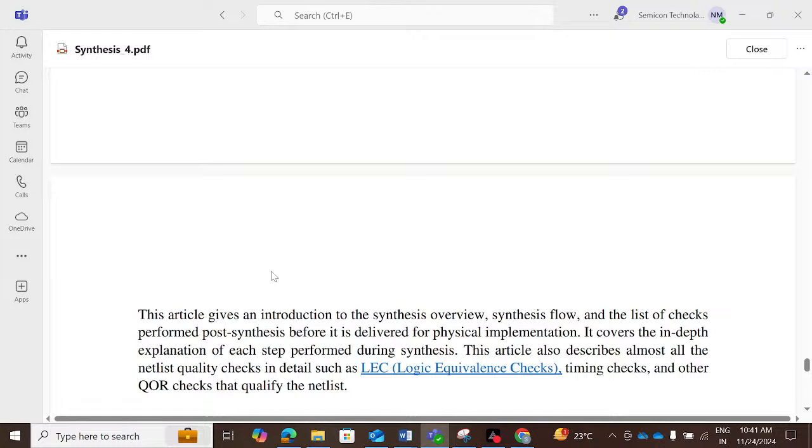Once these things are taken care of, in the physical design cycle you can easily close on PPA because the netlist you are taking as input in physical design is very well optimized. Similarly, at every stage of the ASIC flowchart, make sure that logical equivalence check is done and it comes out clean.